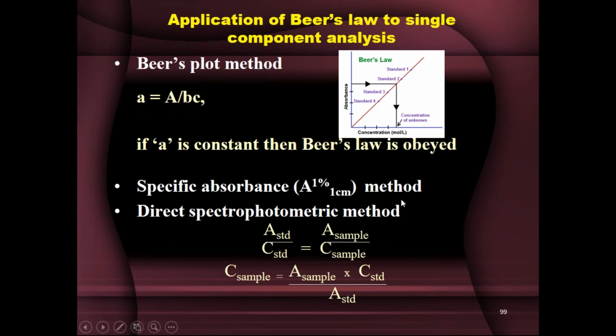Now, the other things which may go wrong is, when you are doing the sample preparation and measuring the absorbance, any errors in the instrument used, any changes in the instrumental response, will get reflected as an error because you're using a standard value prepared under different conditions.